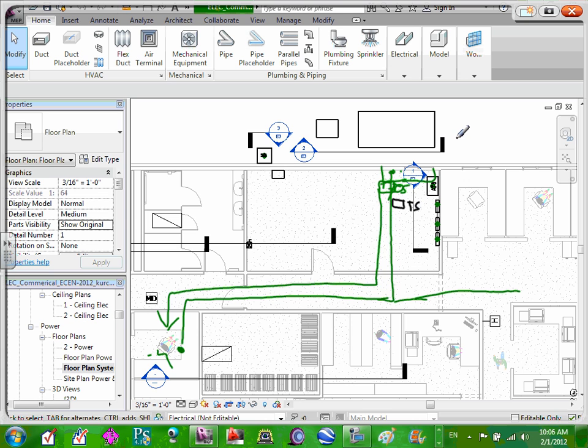And then number 9, connection to fire protection horn strobe located above the Siamese connection on the exterior of the building adjacent to mechanical 116. So the Siamese connection, I'll start there. On the outside of the building, there is, and I'm just going to draw it real large here so you can see it, a place for the fire department to hook up their hoses to tap off of the water for your building.